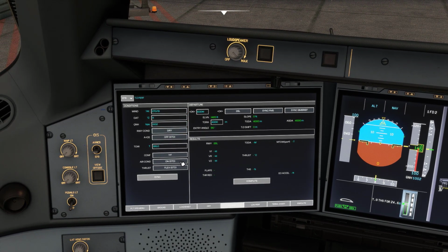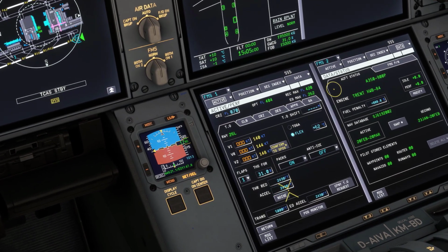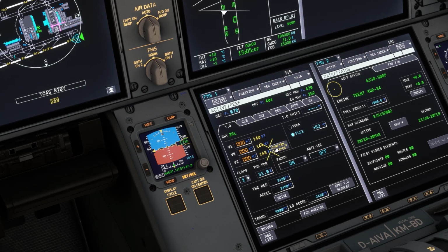And we have this one, wind 2713, and we just compute the takeoff performance. Oops. Okay, like that. It's 148 for V2. Flex to 6, and we can send this to the FMS. Let's see how that works. Yep, that's those numbers, and we confirm them, and flex to 62. Bus detection, we take everything.